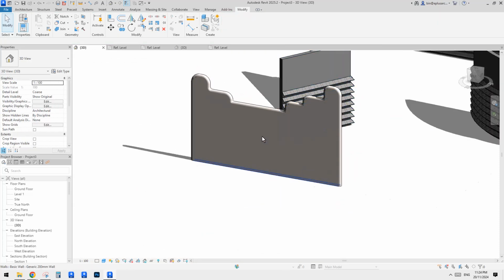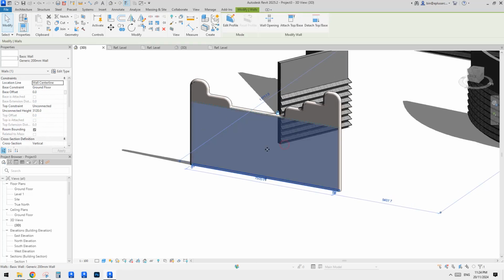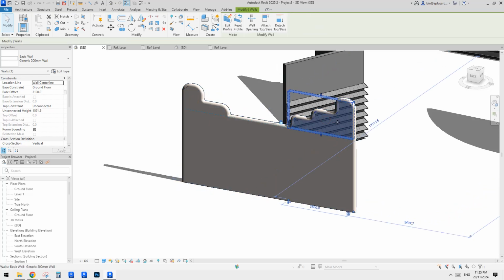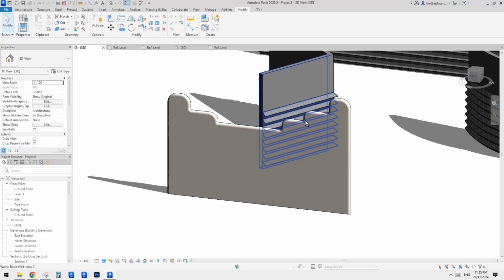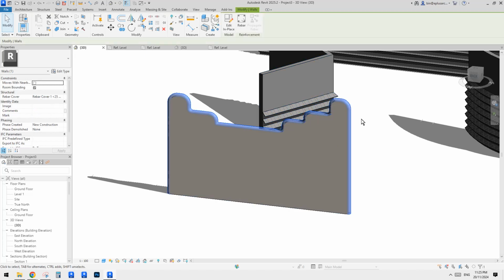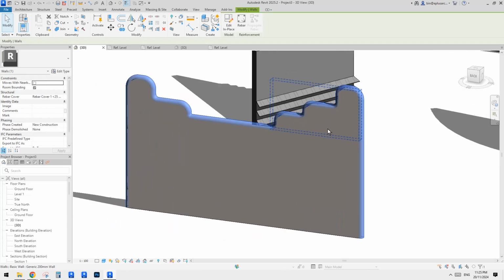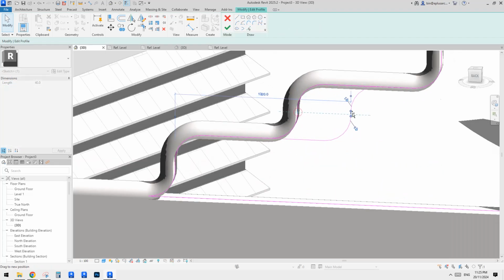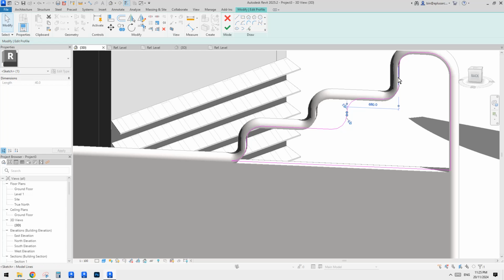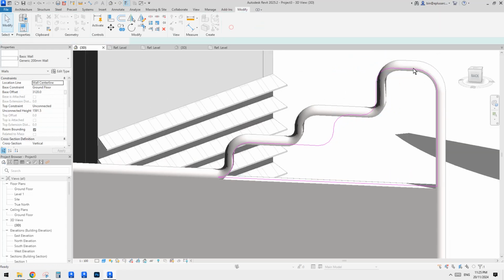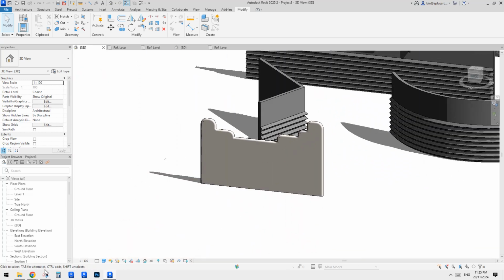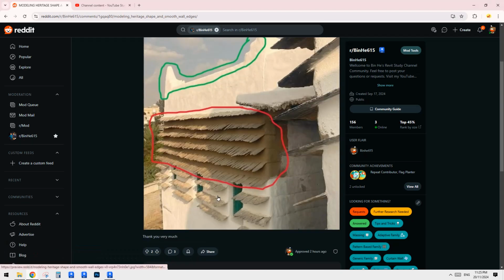Okay, so yeah, this is it. So this is one wall without editing profile, and another two on top with edit profile, and then use sweep and pick path and create that sweep. So it automatically changes to match your wall, right? So when you change the wall, the sweep automatically changes. So, and this is it. Yeah, I think that's all.